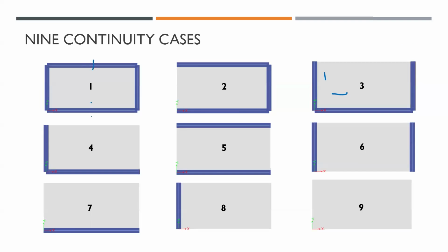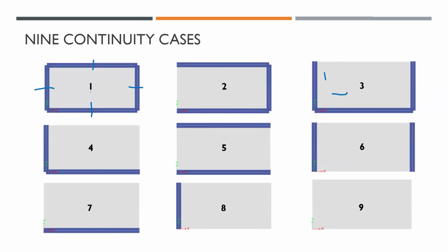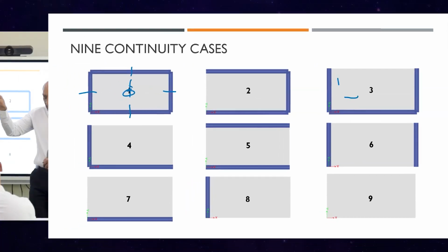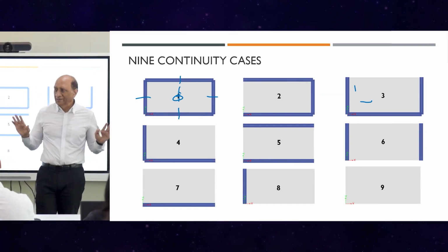Moment here, moment here, moment here, moment here, negative moment, and also gave you positive moment here and positive moment here. So you got 6 coefficients and 6 bending moments for each slab, depending upon the ratio. There was a single nice, beautiful table by the British code with the aspect ratio of the slab and continuity on one side, 9 columns here, you go here, vector there, you are done.